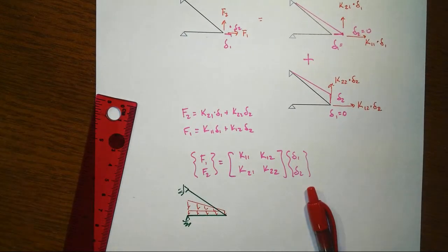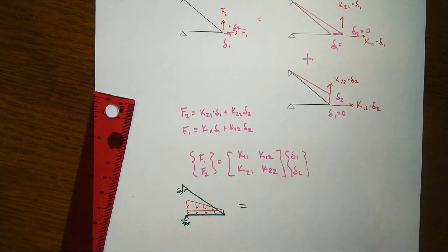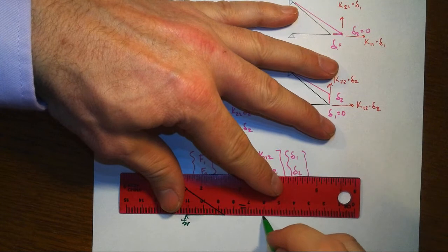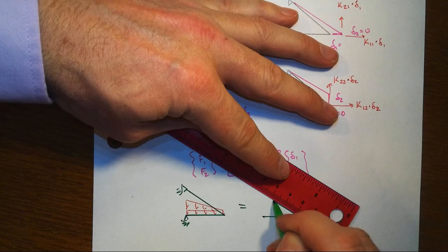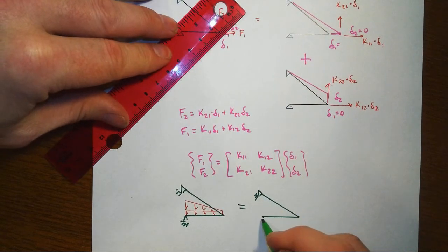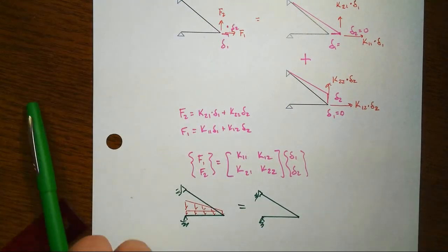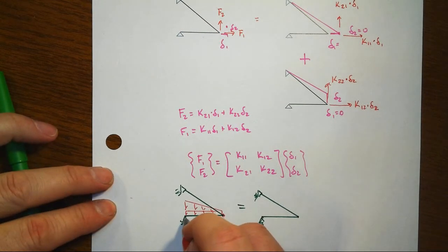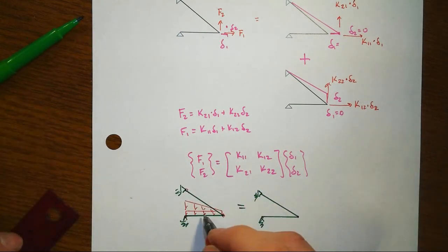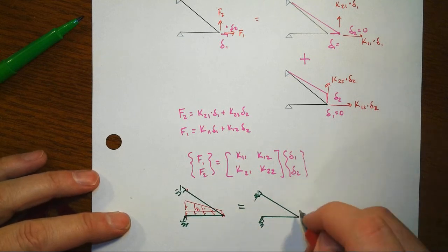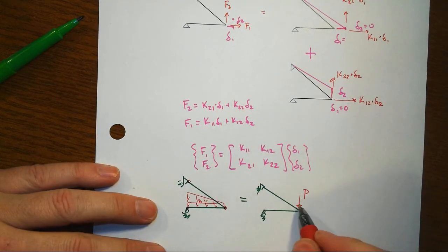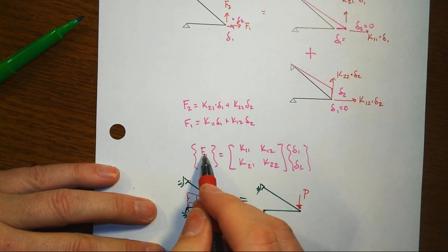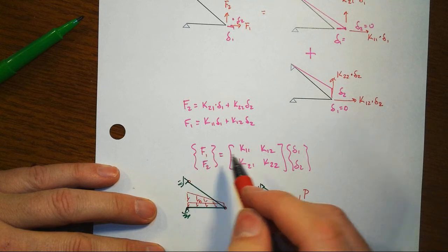In our model then, what we're going to do is create equivalent nodal effects. Kind of like in the slope deflection method when we did fixed-end moments. We do a similar kind of thing here, of fixed-end forces, so to speak, but it's a little easier here because we really do have pin connections everywhere, and so we'll just take whatever the tributary load or the load by equilibrium is, and we'll lump this in as an equivalent model, and now that becomes our F1, F2 values that we're imposing on the system.